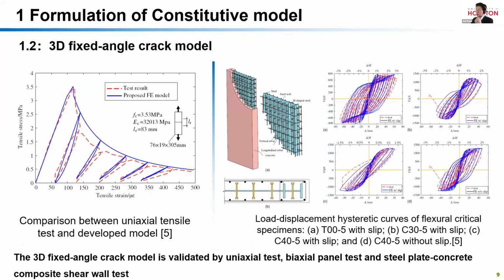This three-dimensional fixed angle crack model has been validated by uniaxial test of concrete, including the uniaxial test and the biaxial test, and also we simulated the performance of steel plate concrete composite shear walls in this research.